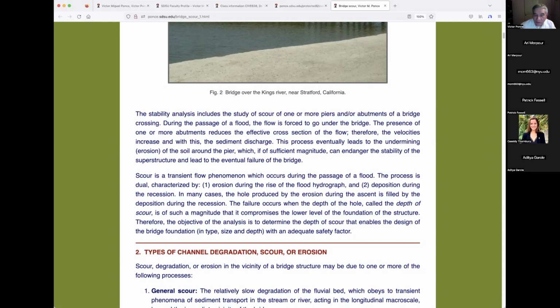So in here, we use a safety factor. Well, of course, in hydrology, technically, there's no such safety factor. The safety factor is implicit in the frequency. So if you say, I don't like the 100-year flood, let me put the 500, and then we go to 500, then you already have a safety factor in there. That's not like structures. In structural design, the safety factor is directly on the load and on the material. So in structures, by the time you apply a safety factor of 3 on the load, and then apply another factor of 3 on the material, then you end up with a factor of 9. And that's the reason why